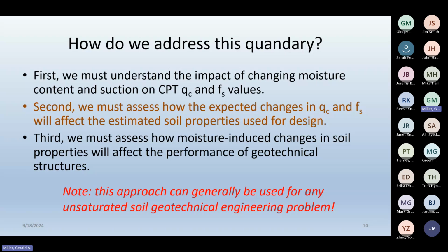So if you're trying to do a forensic analysis and you're using saturated strength parameters, it may not be terribly precise. But if you look at variations in moisture and how that affects shear strength, generally slope failures occur due to wetting and significant wetting, but they may be triggered prior to reaching a saturated state.